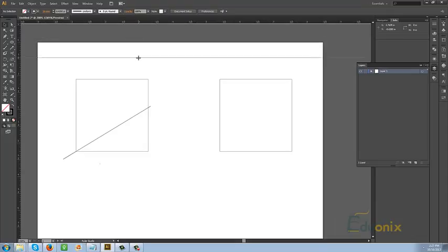So when you're dragging out a guide, if you press Alt, I believe that's Option on the Mac, if you notice, it turns into a vertical guide. Holding in Alt does what it does for many other things. It alternates what you're doing, and an alternate horizontal line or a guide is a vertical line guide. So all I'm doing is holding an Alt when I'm dragging out my guide. Same thing where if you were to drag it from the vertical and hold in Alt, it'll turn it into horizontal.